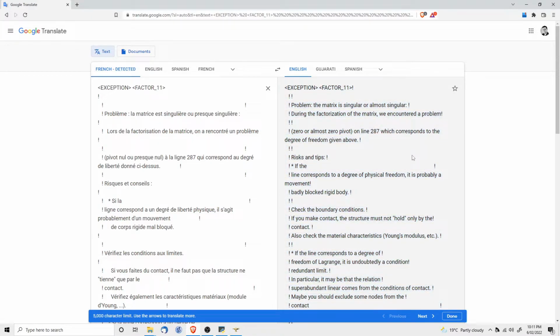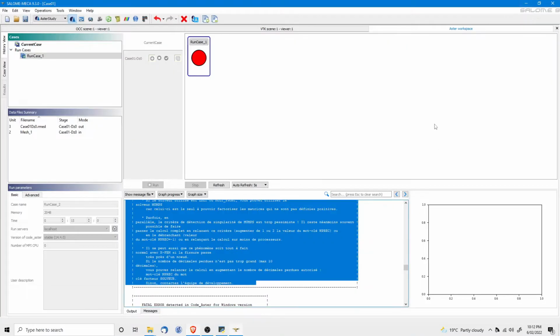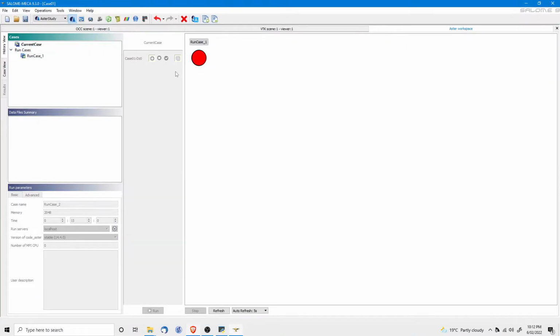Okay, out of all of that, what it generally means is that there is no way that you will be able to hold this analysis. So in other words, if you just provide DZ0, it was all right for PrepoMax, it was all right for FreeCAD, and it was also all right for ANSYS, but for Salome-Meca this won't work. So how about we just keep this case as it is.